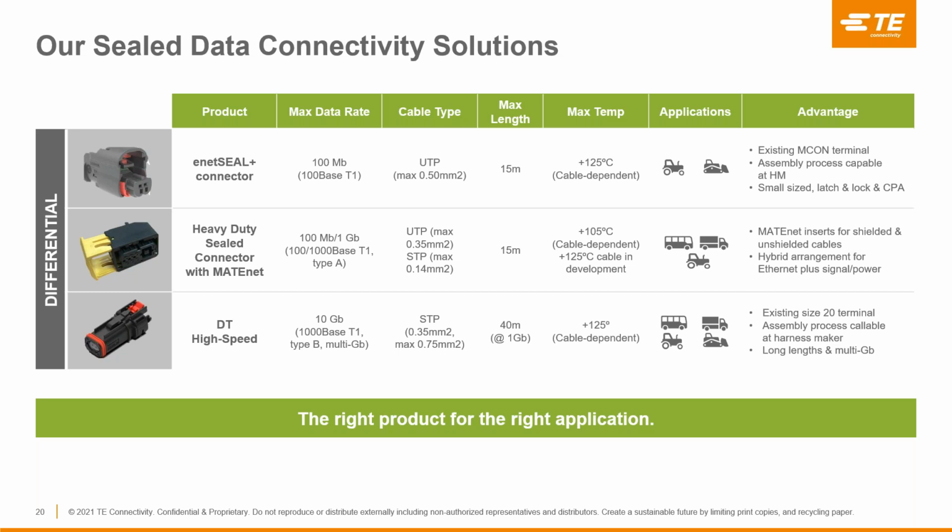This is, let's say, an entry-level connector for automotive Ethernet, where you perhaps can be transitioning for some of your higher data rate needs from a traditional CAN bus architecture to an Ethernet connection. And this runs at 100 megabit speeds or addresses the 100BASE-T1 specification of IEEE 802.3, utilizes unshielded twisted pair cable, works up to 15-meter lengths with 4 inline connections. So again, that would be a total of 5 cable assemblies over that 15 meters with 4 linkages between those, as well as the connections to the board on either end. Maximum temperature 125 C, specifically really applications addressing the agricultural and the construction industry.